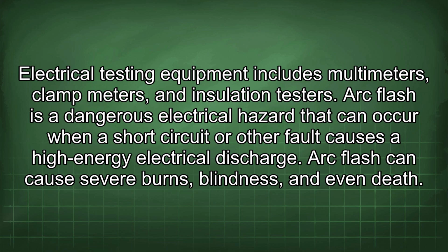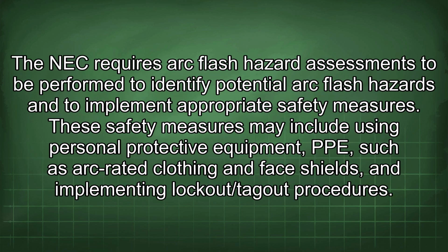Arc flash is a dangerous electrical hazard that can occur when a short circuit or other fault causes a high-energy electrical discharge. Arc flash can cause severe burns, blindness, and even death. The NEC requires arc flash hazard assessments to be performed to identify potential arc flash hazards and to implement appropriate safety measures. These safety measures may include using personal protective equipment, PPE, such as arc-rated clothing and face shields, and